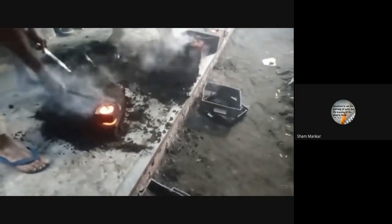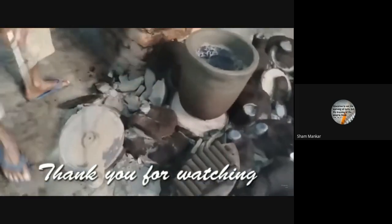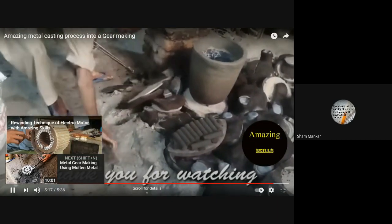Fumes are coming out from that particular mold. After some time we break down the mold, the upper box as well as the lower box, and we remove the casting along with the different elements of the gating system, such as the runner, riser, choke, or skim bob which is part of the gating system. Then we remove the unwanted parts.